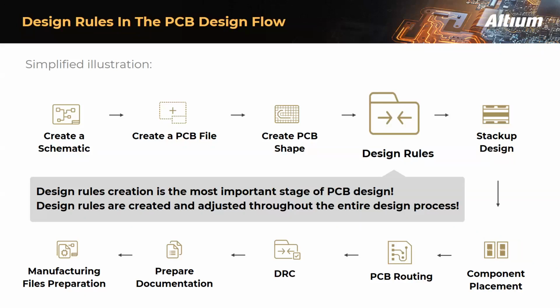Okay, let's discuss the simplified PCB design flow. Every design starts out with the schematics to capture the design intent. Then we add a PCB design document to the project. Once the board shape has been established, it's time to set up the design rules and constraints as well as the layer stack-up. The design rules and constraints go hand in hand with designing the layer stack-up.